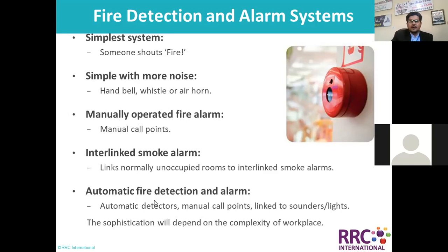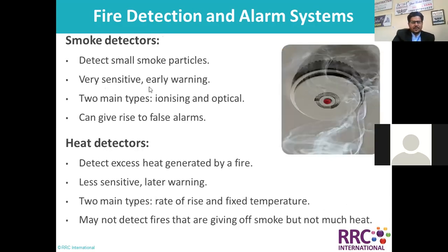Now they have already standardized that you have to implement an addressable system instead of just battery operated. Look at the smoke detectors and heat detectors; they must be capable of detecting the fire or the heat. There are two ways, it could be ionizing or optical. In the same way, heat detectors must detect whenever heat is generated, especially by a fire.